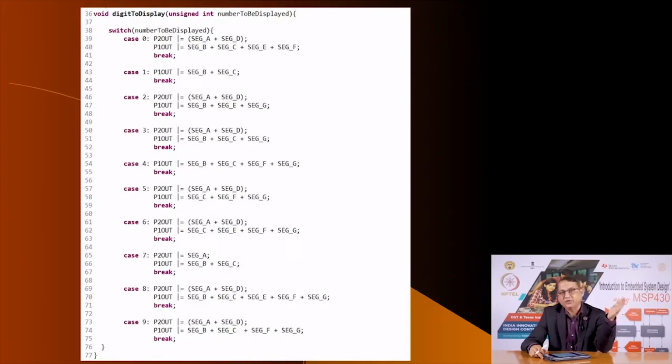So that the interrupt subroutine, especially the timer interrupt subroutine, will be able to pick the count, and based on the value that has to be currently displayed, from that count it will be able to display exactly that count on that digit, and it will happen smoothly.